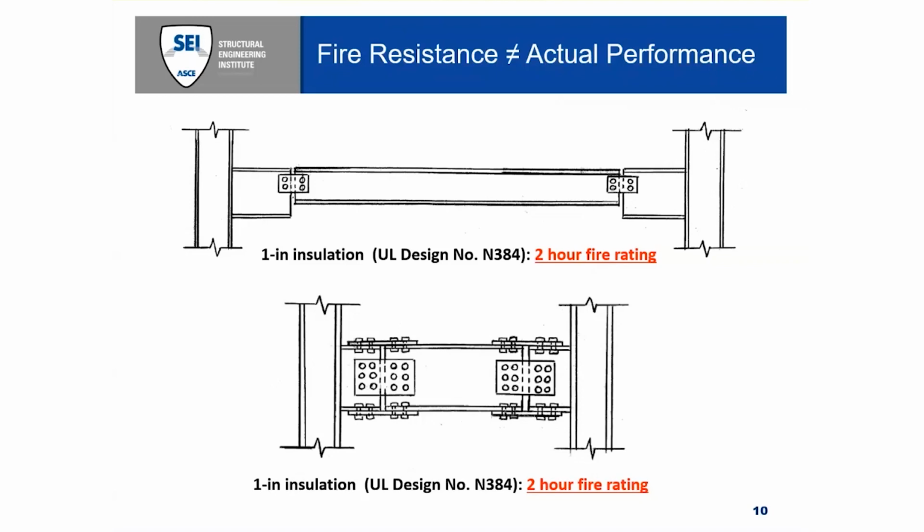Now, this may seem counterintuitive to you, thinking like a structural engineer, and this is because standard fire resistance design does not necessarily credit nor does it discount the capacity of the structure to endure the fire. Standard fire resistance design essentially prescribes insulation with the intent of limiting the heating of individual components in order to have a mitigation of the risk, but not a qualification of the risk.